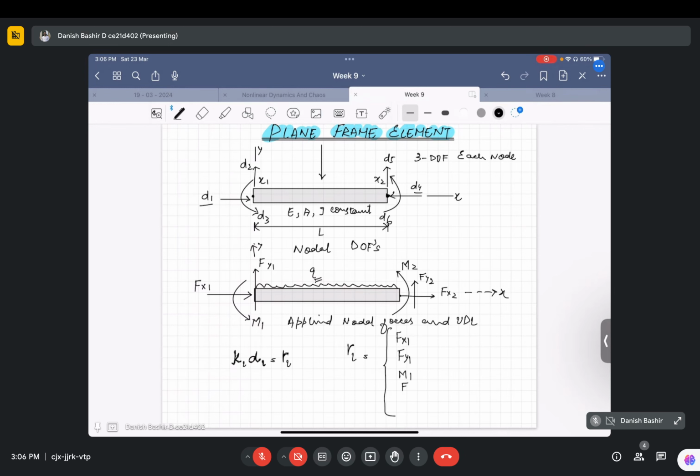Similarly for node 2, Fx2, Fy2, and M2, which is equal to, since it is a uniformly distributed load, 0, QL by 2, QL square by 12. Similarly here again 0, QL by 2, it's obvious, minus QL square by 12. These are the things we are going to get.